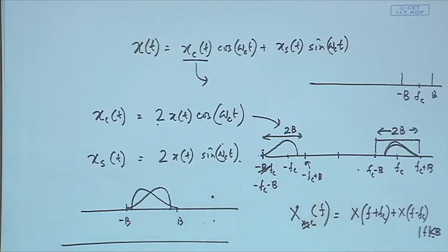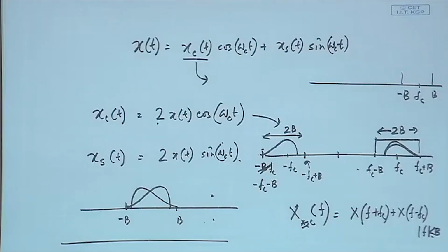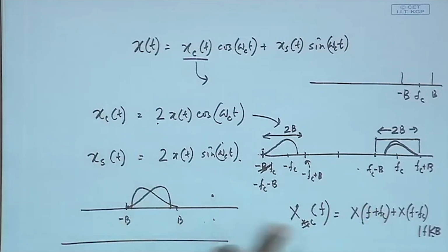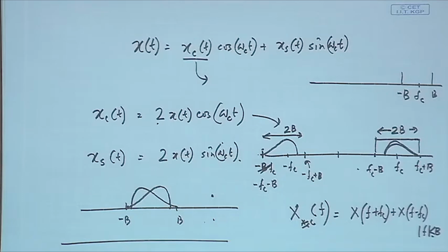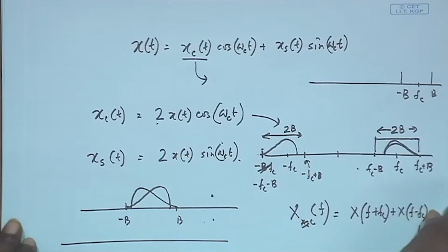All the higher frequency terms will be neglected, it is just these two parts will overlap and whatever I get. Okay. So, that is actually my xc(t) and the corresponding Fourier transform of that. Okay. So, I immediately get the corresponding Fourier transform of this one, right. It is very easy to get directly the Fourier transform as long as I know the x(t), means the power spectral density. So, basically what I can do, instead of doing this, I can relate them in terms of power spectral density.